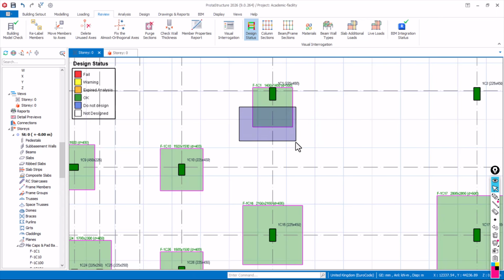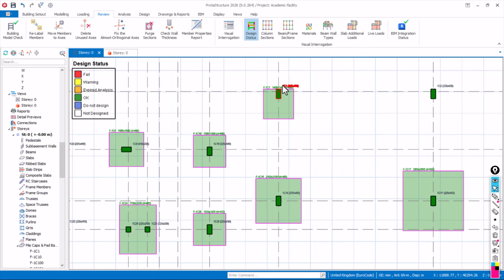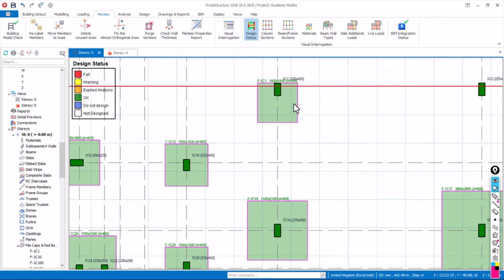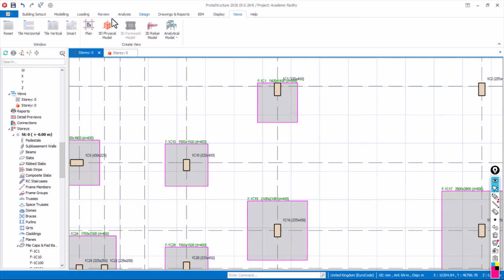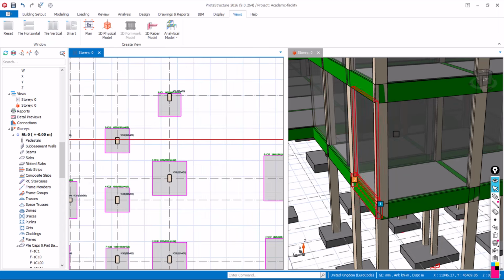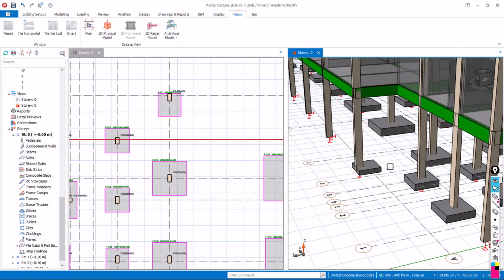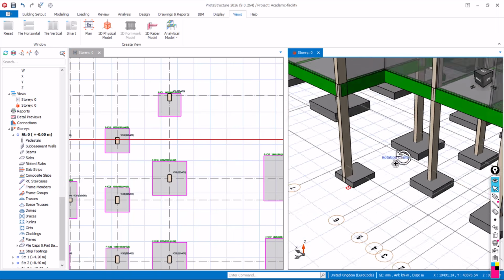So how do we now proceed? You now have to apply your engineering experience, by inserting a strap beam. Right now we are going to model a strap beam on this footing. To model a strap footing, I'll go out from this design interface, and then make my screen dual, to show this and also this here. Now that we have this, the next thing we do is model the strap footing here, and that takes us to the modeling tab.